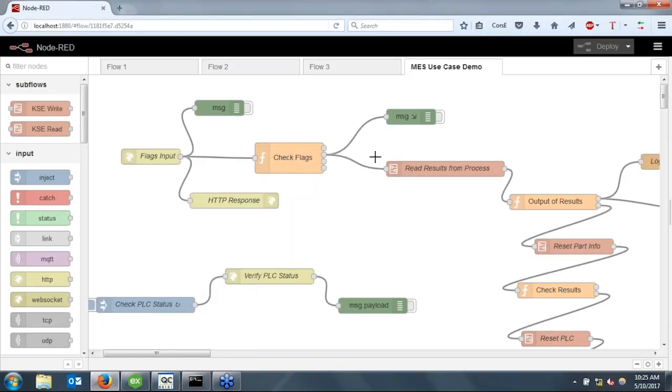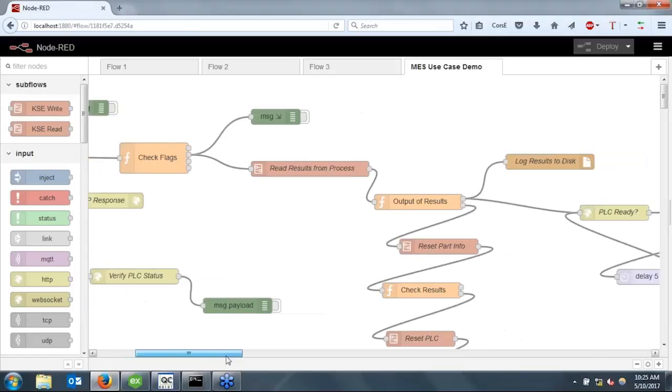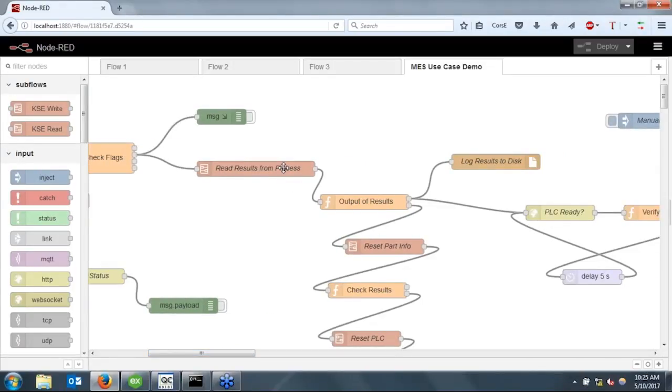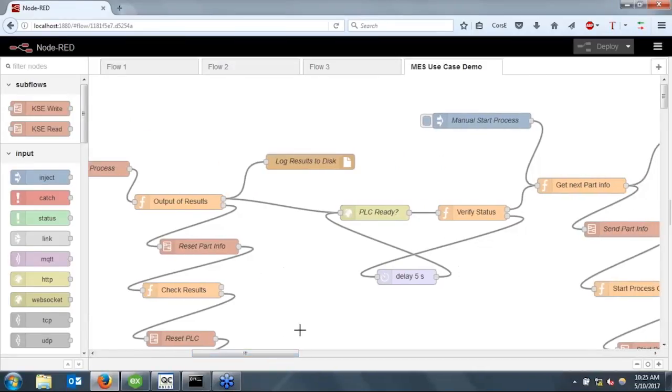So you can see the services provided through the HTTP agents, whether it's the client agent or the server agent, closely resemble the similar services that you need when you're using a manufacturing execution system. The ability to subscribe to data would be done through an HTTP client agent that's going to publish data on data change, or if you need to do explicit reads or writes down to your PLC, a server endpoint in KepServerEX's IoT Gateway allows you the ability to interact with the PLC, similar to OPC services and other services that you would commonly use down on the manufacturing floor.